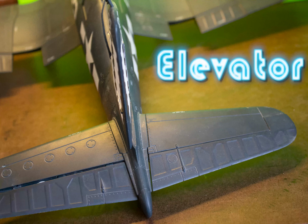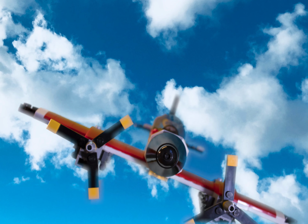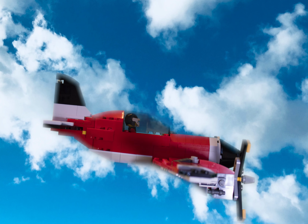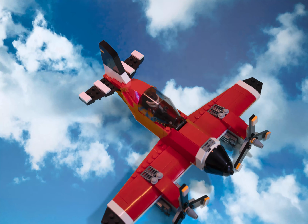The ailerons control the roll by shifting high pressure on one side of the plane and low pressure on the other. The elevators control the pitch, which will change the direction downward or upward, and the rudders control the yaw, which will change the direction of the plane to one side or the other.